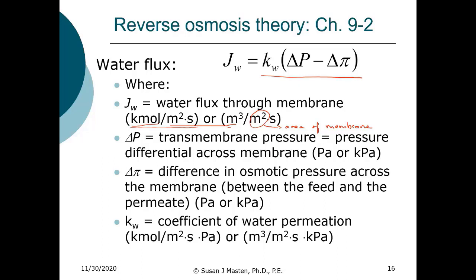And it's dependent on this coefficient of water permeation, which is dependent on the membrane. And notice, it's your flow divided by the surface area of the membrane times the pressure. So it's a specific coefficient, really. Since we've included pressure, it's dependent on the pressure.